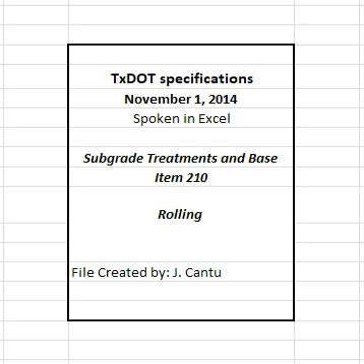3. Construction. Perform this work in accordance with the applicable items using equipment and roller speeds specified in Table 1. Use only rubber-tired equipment to push or pull compaction equipment on base courses. Use equipment that does not damage material being rolled. 4. Measurement and payment. The work performed, materials furnished, equipment, labor, tools, and incidentals will not be measured or paid for directly but will be subsidiary to pertinent items.